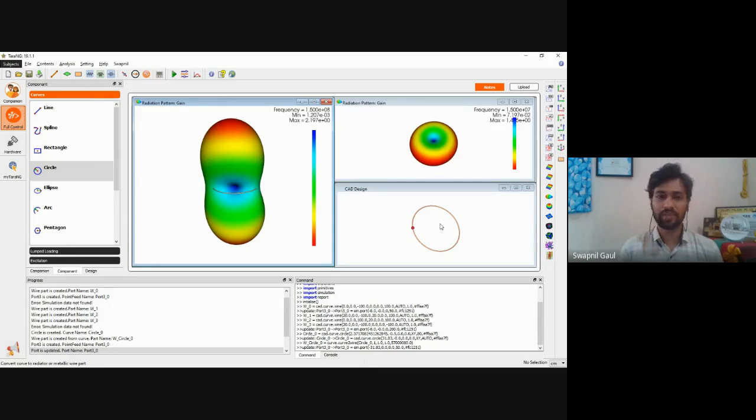And the second benefit of that helical transmitter is that we are getting a circularly polarized signal. In the case where we have a vertical dipole antenna, and at the receiver we have a vertical dipole antenna, then only we will get the signal. But when we have a vertical dipole and at the receiver we have a horizontal dipole, then the received signal will be zero. That polarization mismatch will happen.